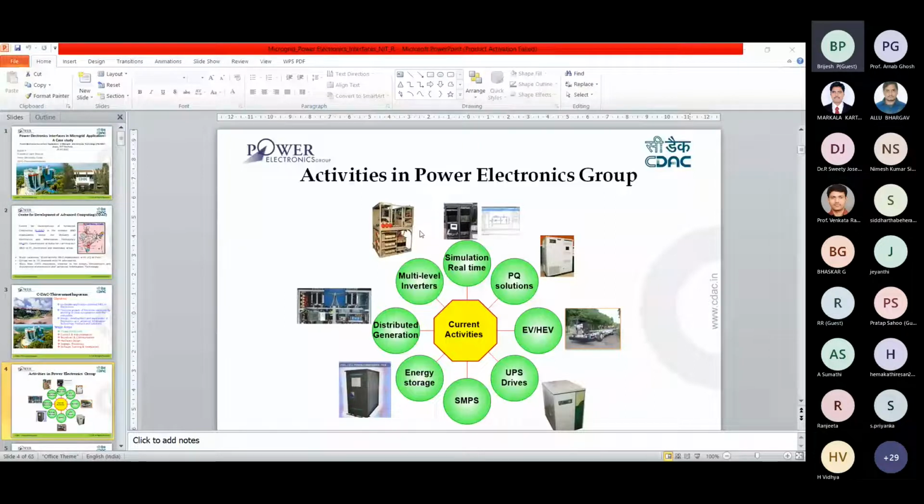So there are different schemes of microgrid based on your application. You can have a DC microgrid. You can have different energy resources like solar, wind, fuel cell, battery storage, or even a diesel generator, and everything can be converted into DC, and you can have your loads on the DC side, and also with a single point you can connect it to the utility grid.